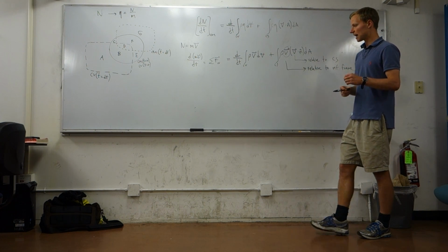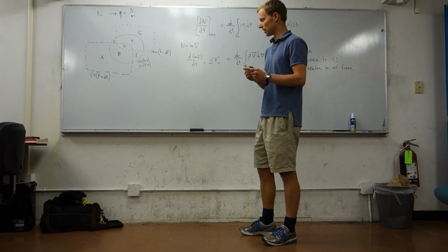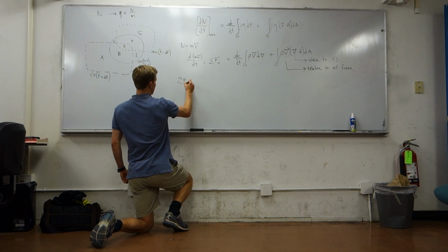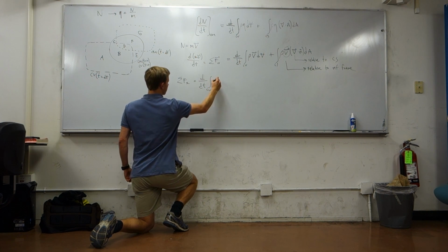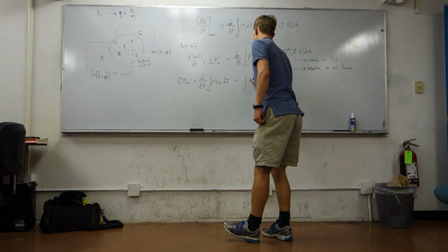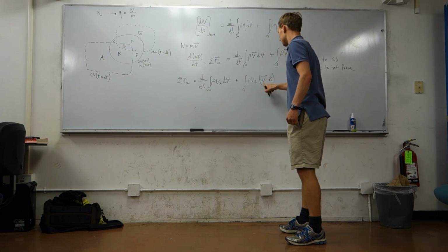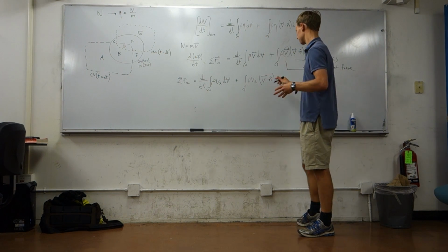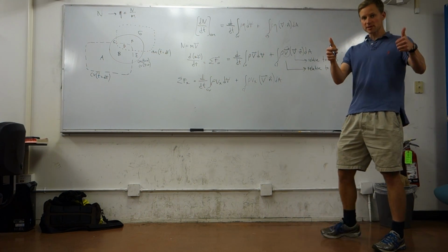Okay, so now in this lab we're going to be applying linear momentum balance to the x direction. So we'll just do a single direction of balance. We can apply this whole equation just to the sum of the forces in the x direction. And our quantity we're balancing is now Vx, which means this velocity now becomes Vx. But it does not mean that this velocity is Vx. Remember, this velocity is always the true vector in three dimensions, dotted with the outward surface normal, times dA. Okay, good on momentum balance?